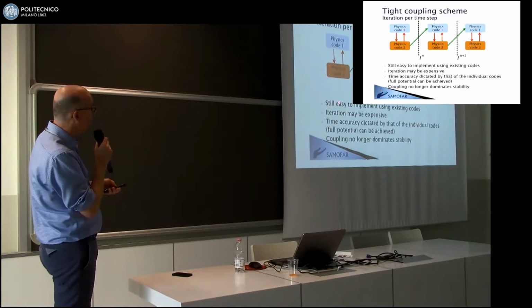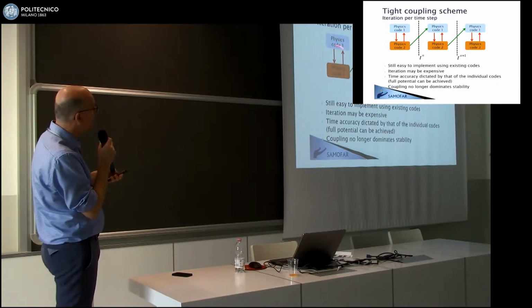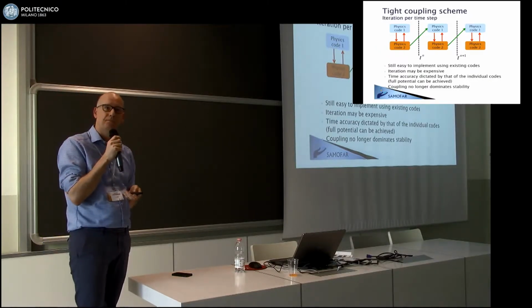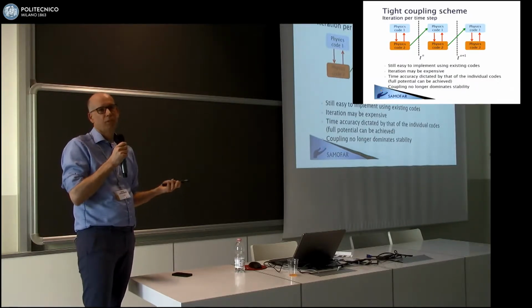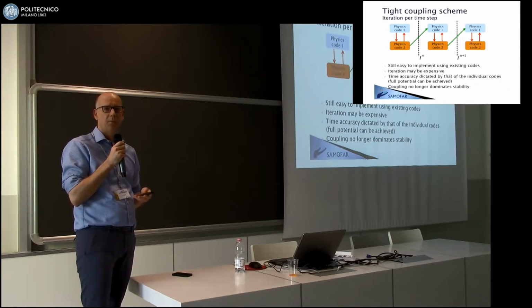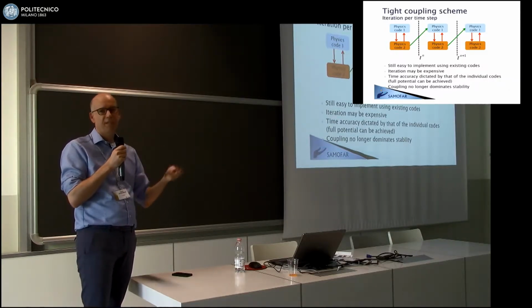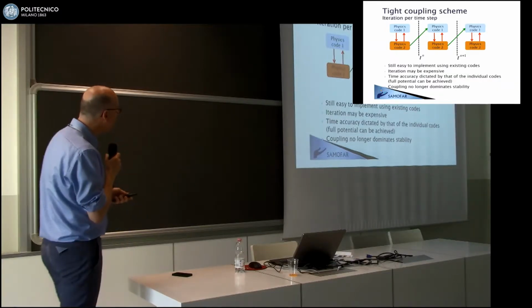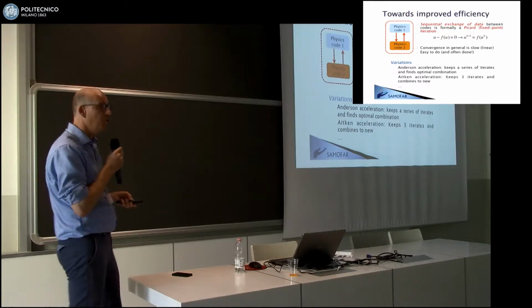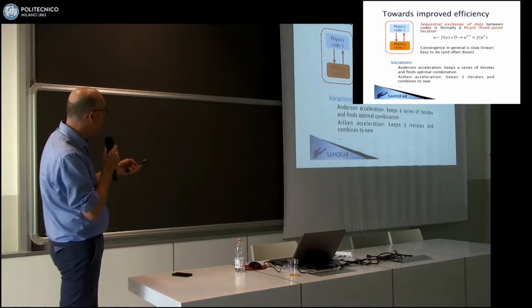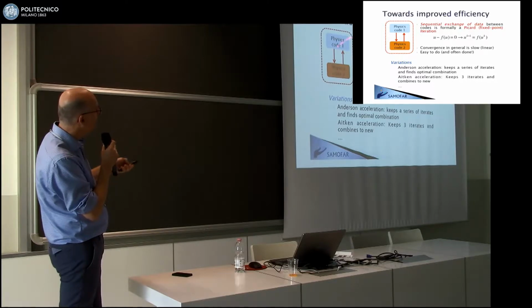Now it's still easy to implement, but the efficiency really depends on how long this takes. That is nonlinear iteration. How many times do you need to do that? Now, in practice, if time steps are small, usually that goes pretty quick. So let's say you do 3 iterations or so. But if time steps are larger and larger, then you get yourself into trouble. So to increase efficiency then, it's all about this within a time step to make this efficiently happen.